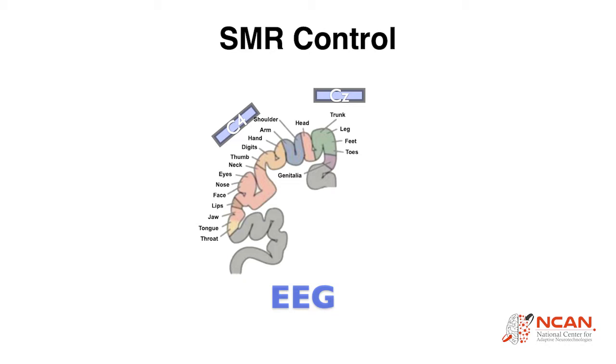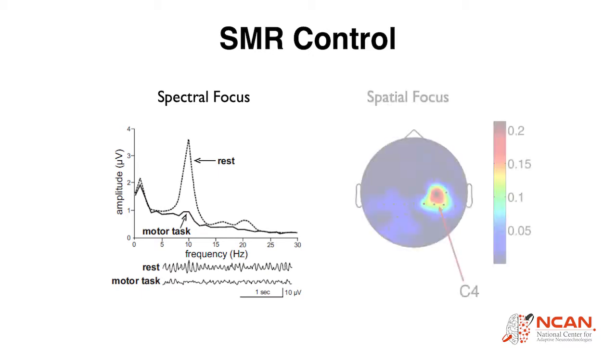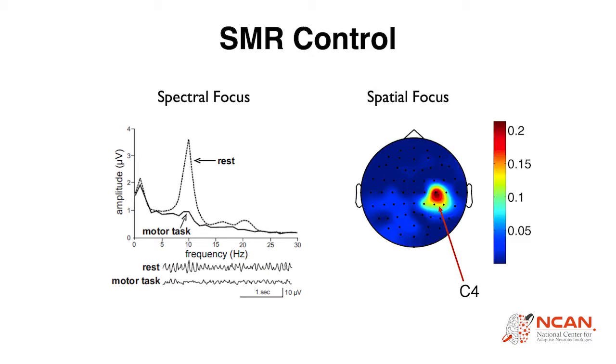hand. In human EEG, primary sensory or motor cortical areas typically exhibit rhythmic activity at a frequency of approximately 8 to 12 Hz when they are not processing sensory information or producing motor output. If the subject moves his or her left hand, we can expect to see a reduction in sensory motor rhythm power around channel C4. We can then associate that reduction with a desired task, such as moving a cursor on